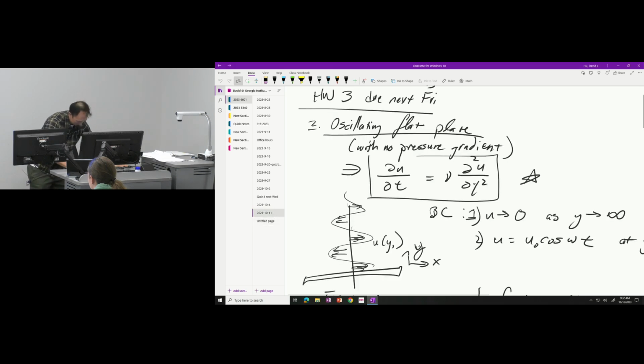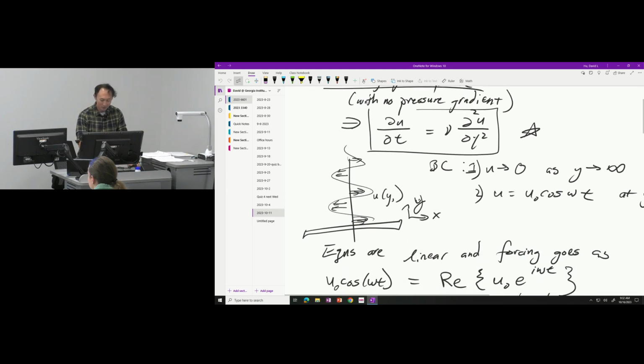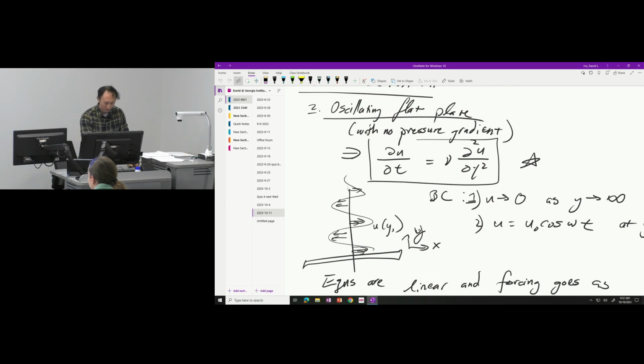All right, to review, we've been doing these Rayleigh problems. We finished the Rayleigh problem, which was basically a plate going to the right at constant velocity, and we saw that there's a velocity field that formed at a distance from the plate that depends on time. At short times you get some motion near the plate, and as you go farther and farther away, you get more motion. Now we extended that approach. The governing equation was the following, because we had the velocity in the x direction as a function of the distance from the plate, which is y. The time dependence is the fact that the plate was not moving at time 0 and then became moving, so there's some information on time that goes into the problem.